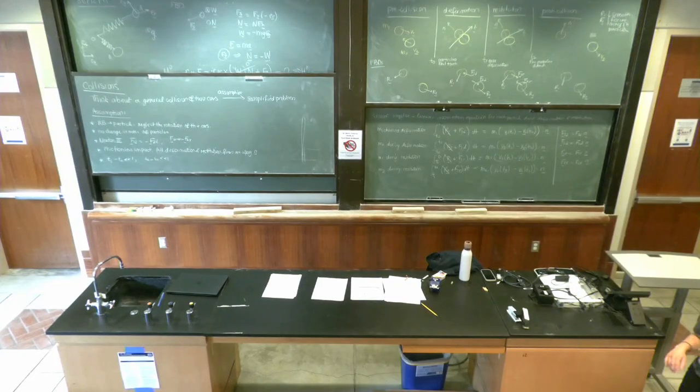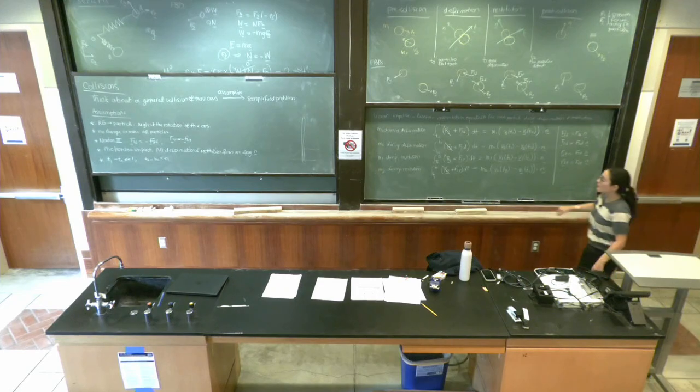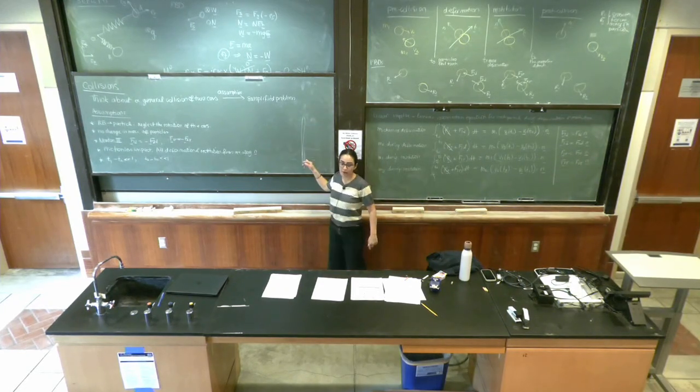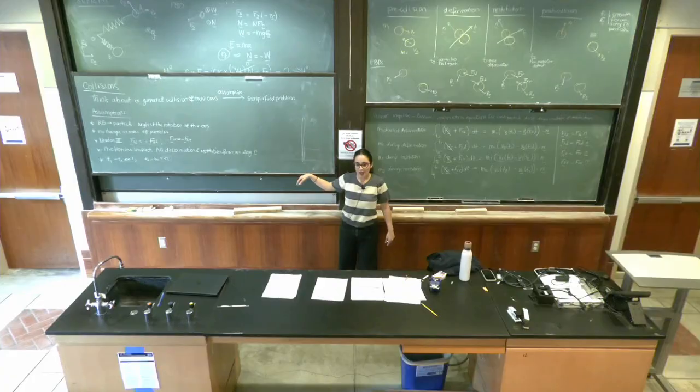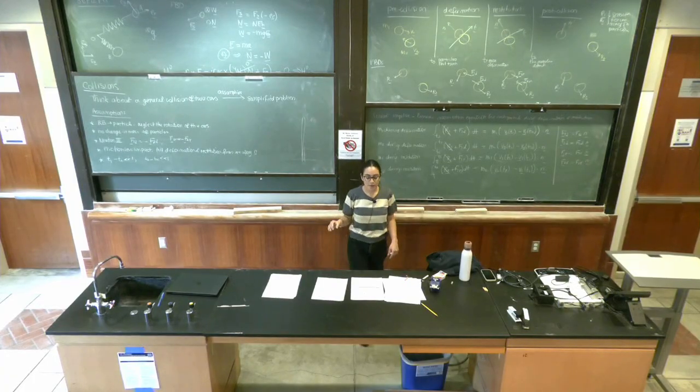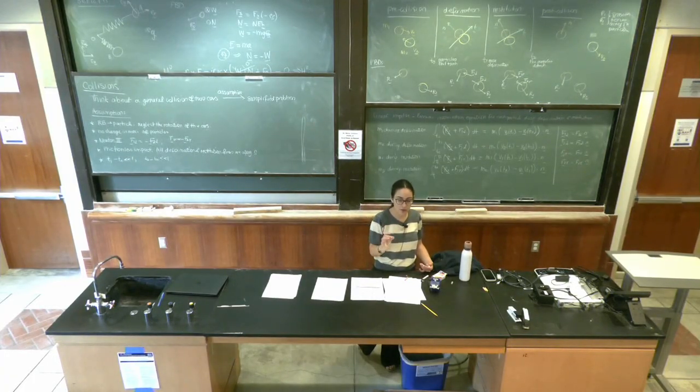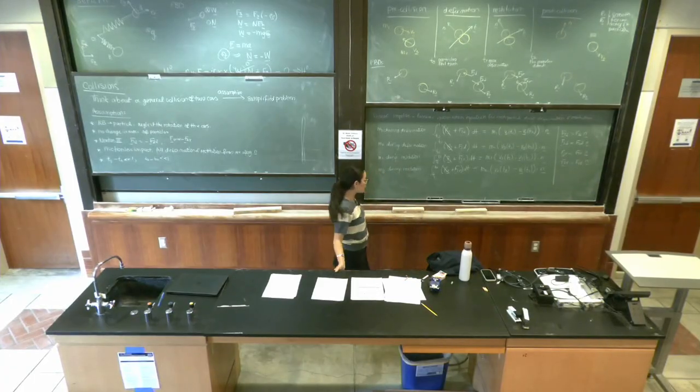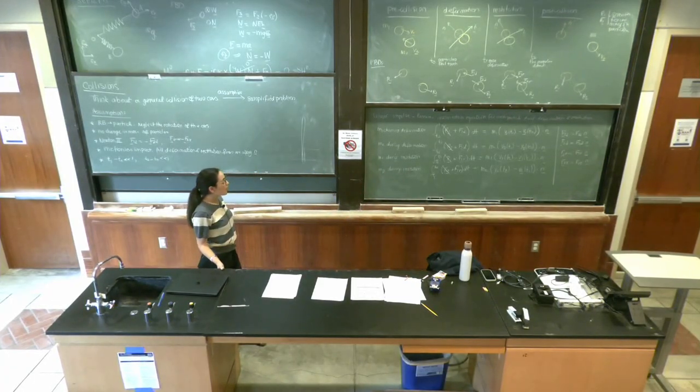Yes? I'm a little confused why only the smooth forces become 0. If the time interval is 0, wouldn't that whole integral just basically be 0? That's a great question. So the smooth forces, yes, go to 0, but the impact forces are going to be infinitely large during the interval of impact. When I'm integrating a smooth function of low magnitude over a small interval, it's going to go to 0. But if something is going to infinity, the integral is not going to be 0. Yeah, that's a good question. Okay. Any other questions?